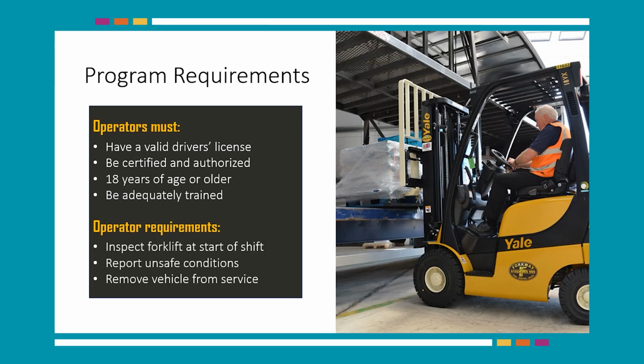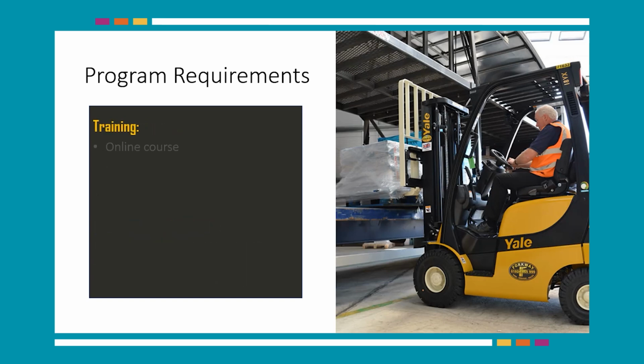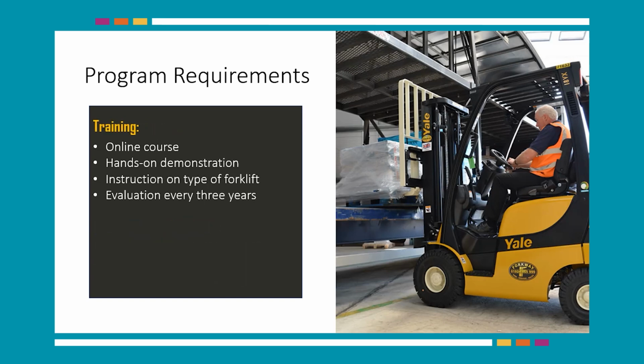Operators are required to inspect forklifts at the start of each shift, report any unsafe conditions immediately to a supervisor, and promptly remove defective forklifts from service. Training is required prior to operating a forklift.